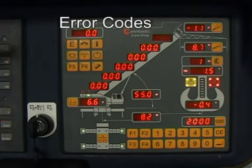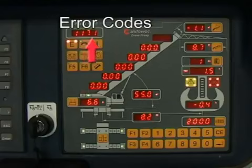Flashing LEDs on the error button indicate detected errors. Repeatedly pressing the button will cycle all error codes that may exist. The 4-digit error code comprises 3 different numbers. From left to right, our example shows 1 as the error group, 17 as the component, 1 as the type of error. You can acknowledge an error by pressing the CE button.